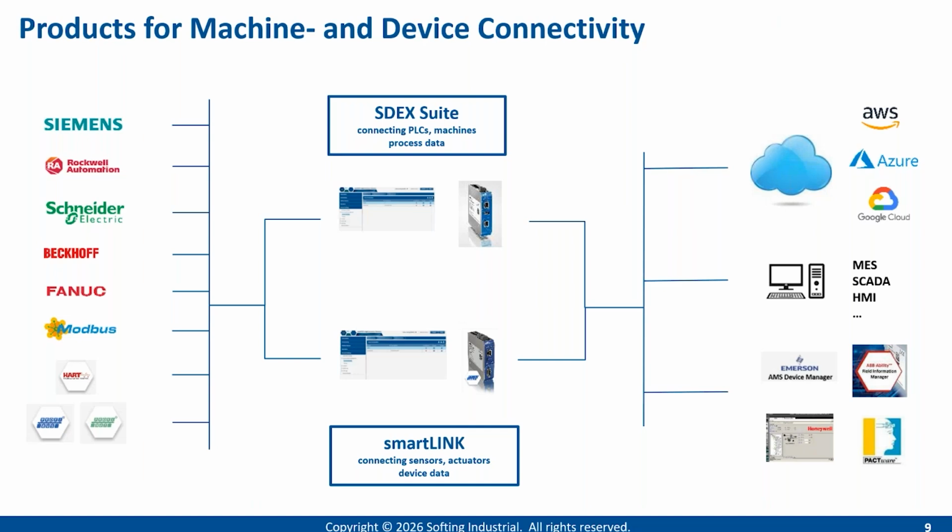We want to connect devices, sensors, actuators, could be a HART device, a Profinet device or a Profibus device, others, which you also know how to connect. At the right-hand side, which kind of applications do we enable, or where can applications run? That potentially can be very different things. Traditionally, at the center, we have on-premises maybe an HMI, SCADA system, MES application running.